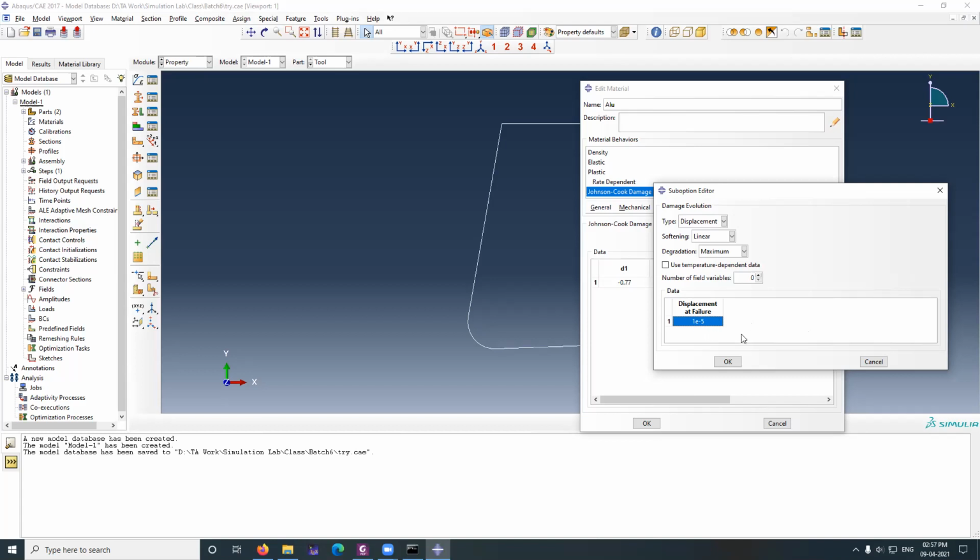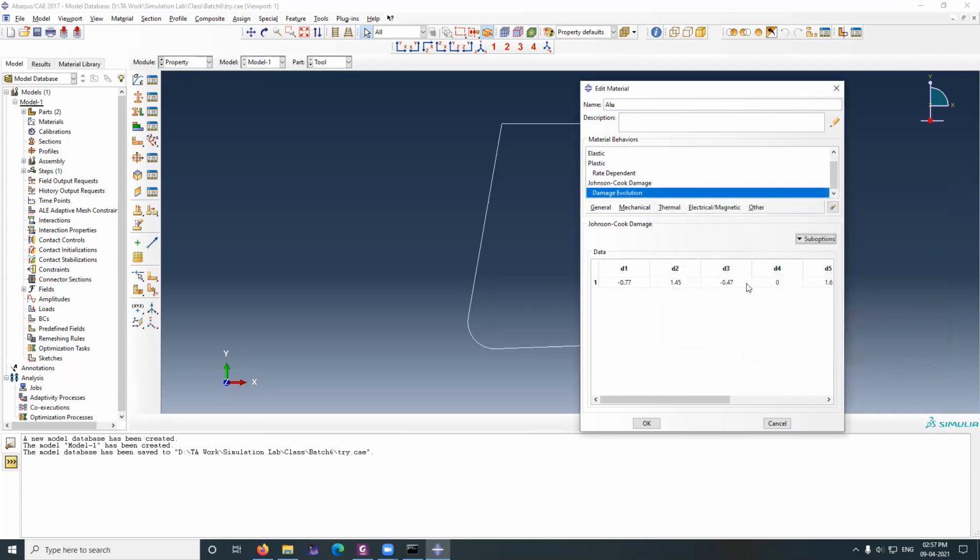Okay, so why I'm giving that is you should get number of nodes less than 1000. So accordingly I chose that number. According to the 5e-5, you have to reduce your displacement or failure number, maybe 1e-5, 2e-5 you can give. So this 1e-5 works very good for you. So keep this number. Okay, I will come back to this point again.